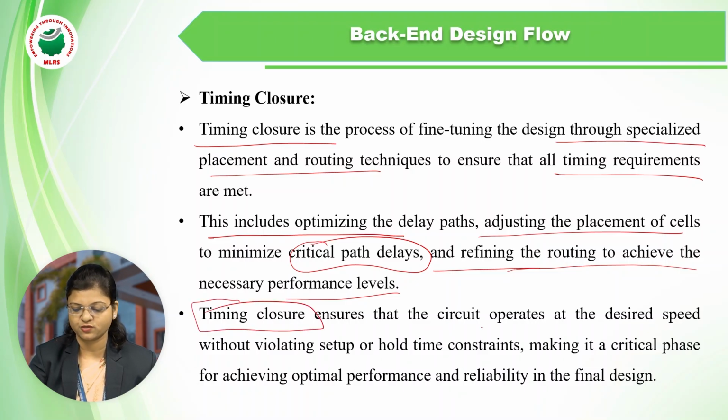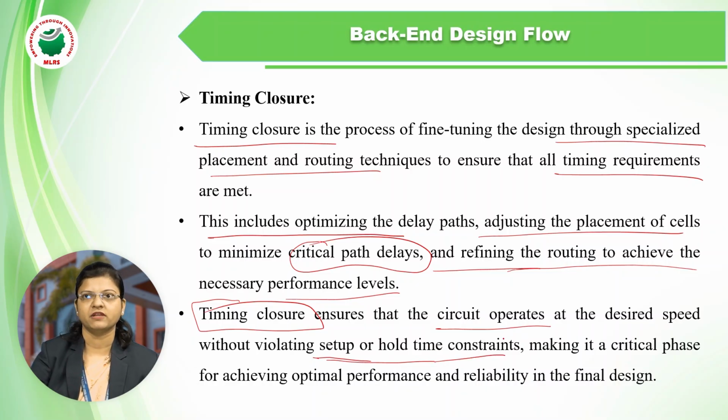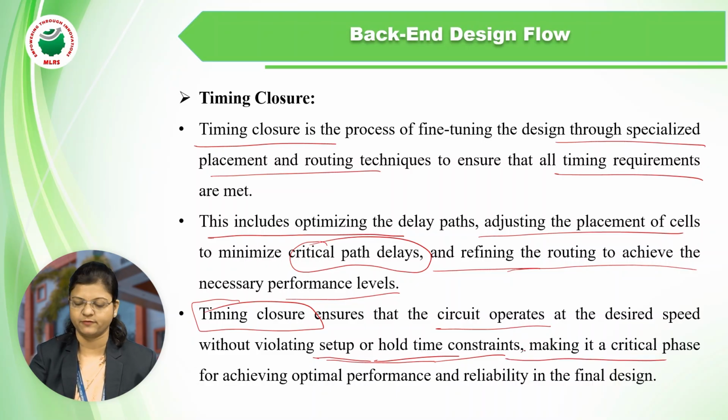It will ensure that the circuit operates at the desired speed without violating setup and hold time. Setup and hold times are the constraints, where setup time is nothing but the minimum delay time before the clock edge, and hold time is nothing but the minimum interval of the delay time after the clock edge. So we should not disturb the setup and hold time constraints. For that, timing closure plays a very crucial role.